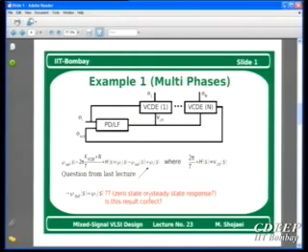Be careful, this is the 0 state response, not a steady state 0 input response. Okay, do you know what is the difference between 0 state and 0 input? If you have a system, just a linear system, this linear system has some sort of state equations. These state equations define the relation between output, state variables and input. If I don't have any input to that system, but somehow because of some problems, that system is not in an equilibrium condition.